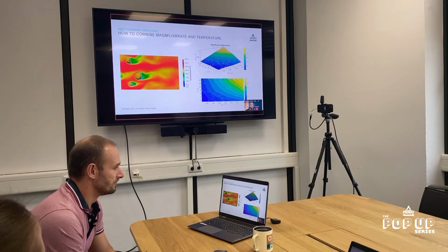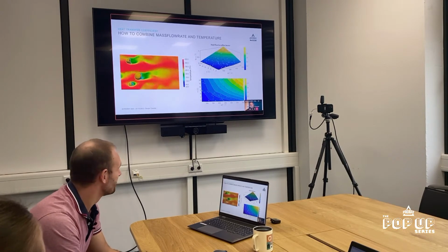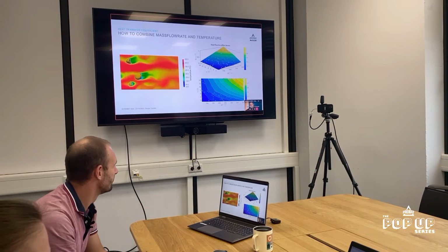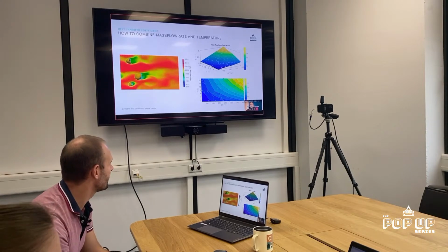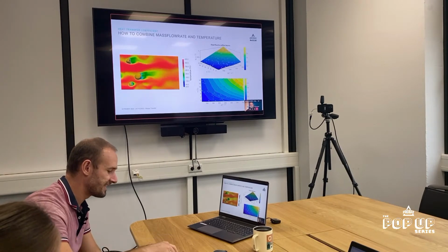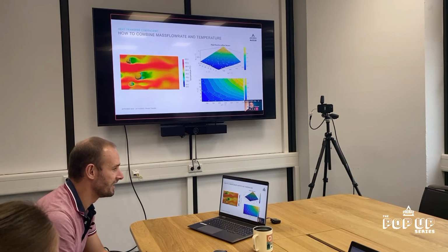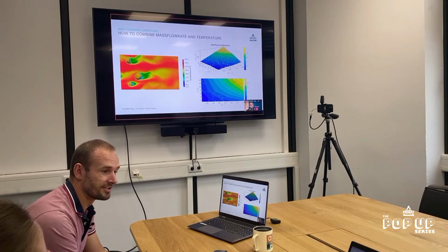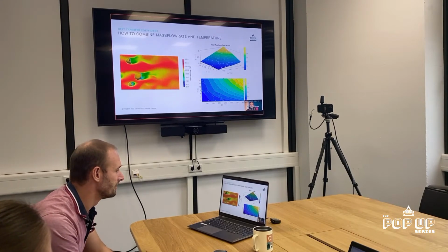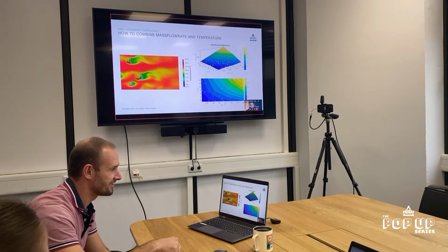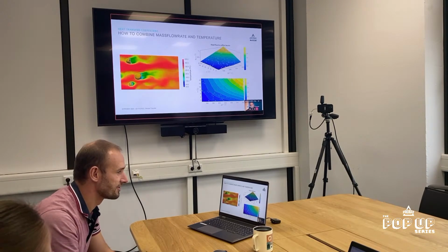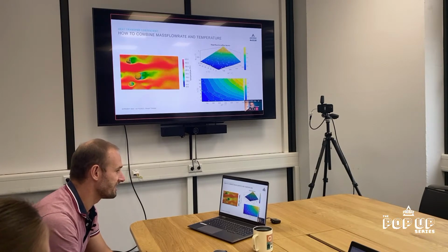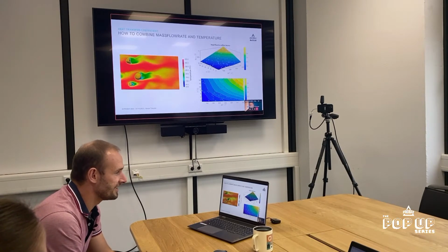And I don't know if you can see it online, but on the bottom right, there's a graph which has solid lines on it. Those are lines of the same energy input to the coffee bean. And on the left, there's the air velocity. And on the bottom, there's the temperature difference, which is shown. And those solid lines transfer the same amount of energy to the coffee bean. So as long as you have a combination of velocity and temperature which stays on this line, you're going to transfer the same amount of energy, which transfers to different roaster types.